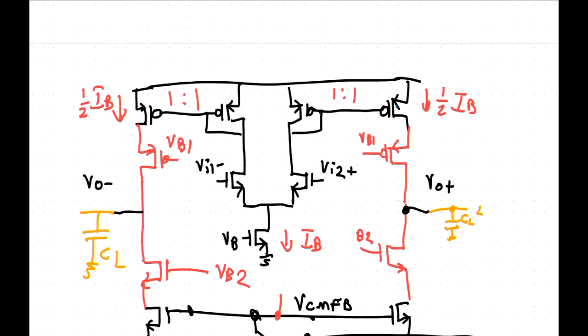Another question is, what about a single op amp without any external feedback? Oh yes, because of asymmetry, there are offset errors and so on. You can't use an op amp without feedback. But for a normal voltage op amp, it's just a comparison. Then it's just a comparator. Yeah, that's right. So, kind of.